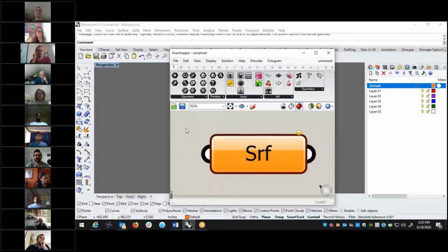Right now it's yellow. If I hover, it's going to tell me it's looking for a surface. It contains a collection of generic surfaces. This goes along with every Grasshopper node. You can hover and it'll tell you what it is. In different nodes, you can even see what inputs or outputs there are. This little flag says the floating parameter surface failed to collect data, and that's absolutely true because I haven't done anything yet.